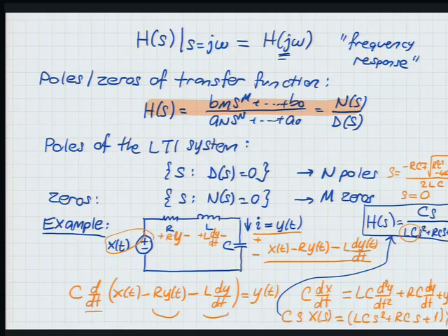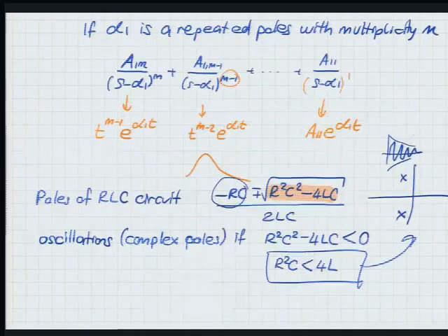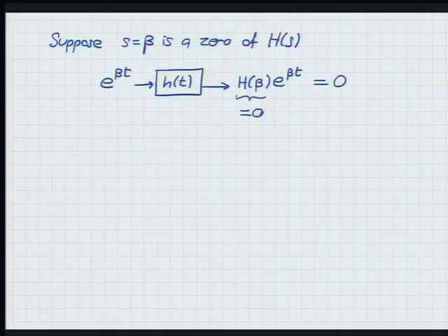So that basically means you can have a constant input, the output will be 0, which is consistent with the structure of the circuit. Because if I have a constant voltage, the steady state current will still be 0. The voltage in the capacitor will balance that out after some transients, and they'll settle, no current will flow. So that's basically the meaning. These types of zeros tell us about the types of inputs that will be blocked by the system.